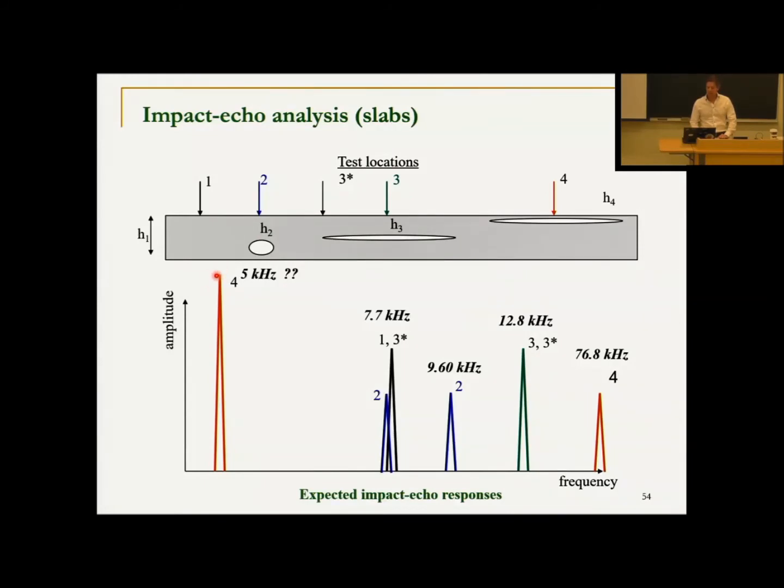It has very low frequency, very high amplitude. And you can say, yeah, but you told me that according to that formula, the frequency should be up here. And that's because this formula, which controls these peaks, assumes a full thickness stretch mode of vibration, not a thin membrane drum mode, which is a completely different kind of behavior.